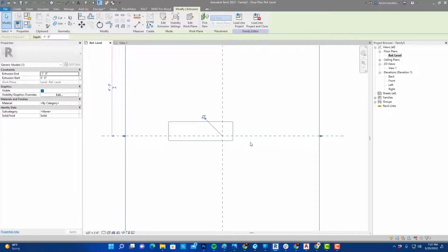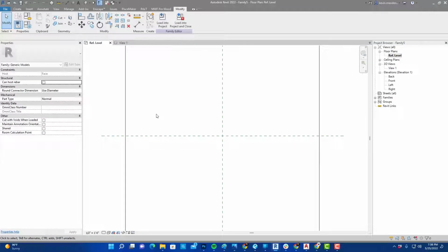if I draw our trim, and that's what we're doing here, draw my trim so the length of it runs left to right, and I keep that in mind with everything that I create, that I will draw it in the orientation that I want the wood grain to run or whatever. So if I have a long board that's running in this direction, I would obviously want the wood grain to run the length of the board.